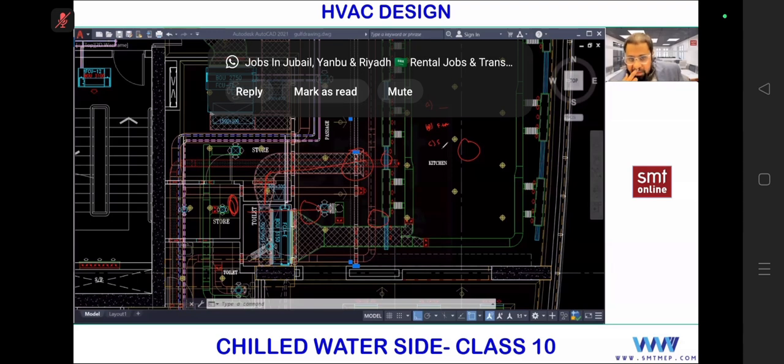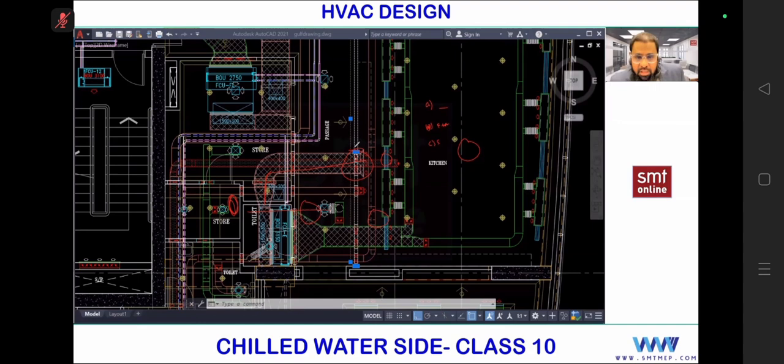Next point, return duct with fittings and accessories. And you see here in this case partly return duct, it is a complete return duct. In that case again you need to apply the critical path for the return A duct also. In bracket critical path if applicable, like this elbow or any VCD or some bell mouth, etc. And then this one is? This point you can write return A terminal. These are the items you need to consider for ESP calculation. Next, this is case 2.